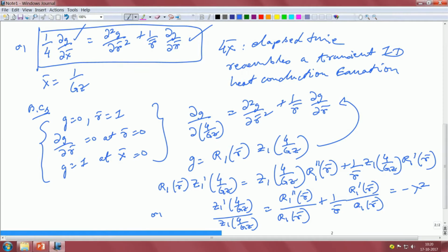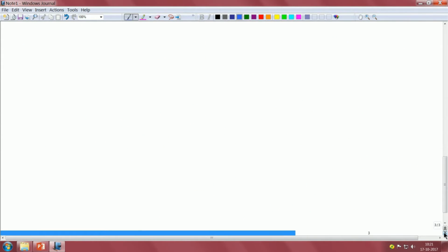Once again, I have told you the significance of choosing minus lambda square. Otherwise you get an exponential term which increases. Here the solution has to be always bounded, so you cannot have that exponential increase. Mathematically speaking, plus lambda square is an equivalent solution, but from a physical point of view, it cannot be the case. That is why we have written it like that. We covered that in our earlier class on thermally developing flow, so the same analogy works here.